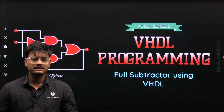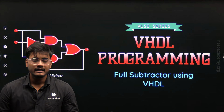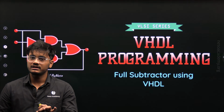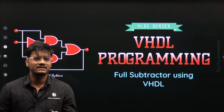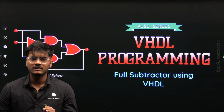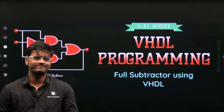We are implementing combinational circuits using VHDL, and in the previous lecture we have implemented the half subtractor using VHDL, and we saw that half subtractor can subtract two single bit binary inputs and generate the outputs difference and borrow.